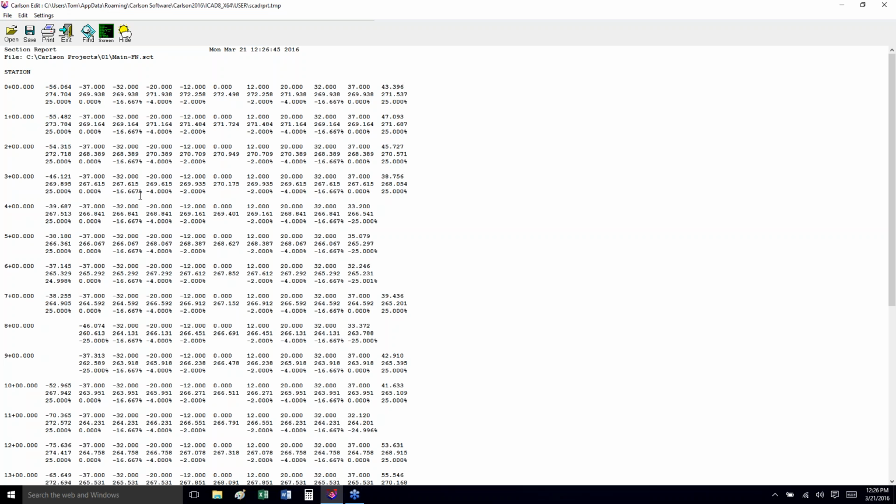This is a nice format for the guys out in the field. You know, centerline, offset, elevation, and slope. It's very basic, but it's really at centerline grade. So this is, and stationing over here. This is very nice for just the guys in the field doing stakeout.